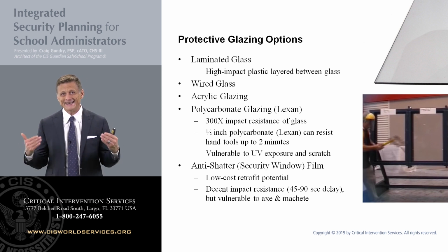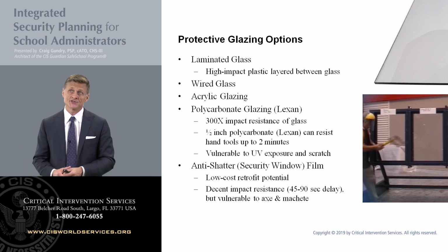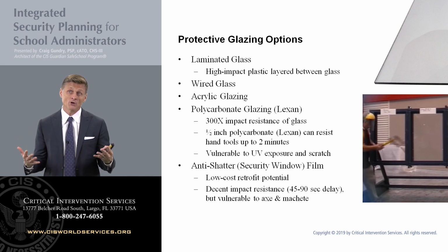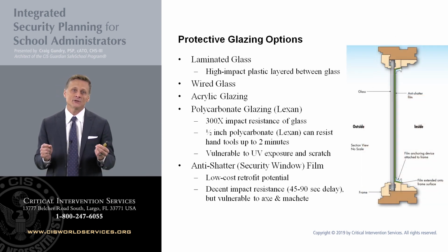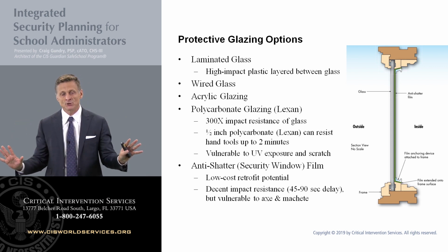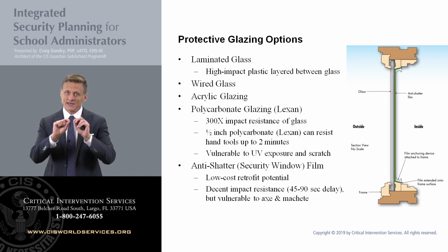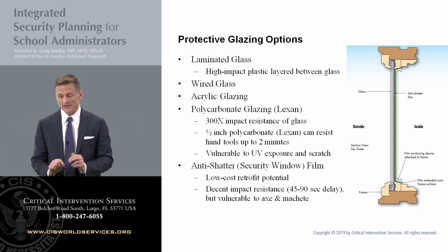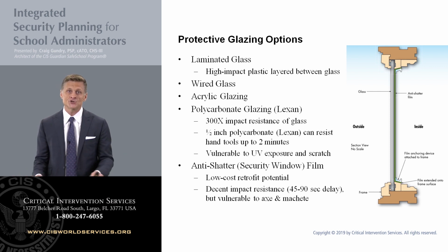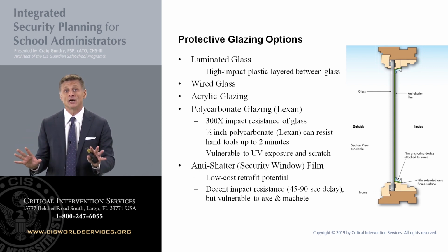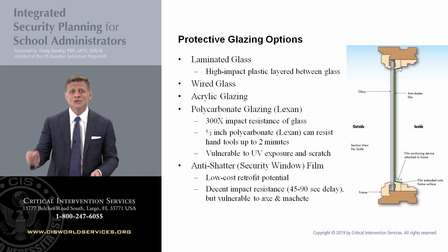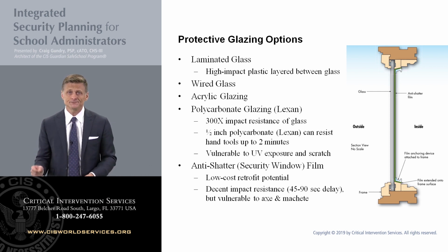Another option for upgrading existing tempered glass windows, and in some cases, especially if we have a lot of windows that need to be addressed, one of the most cost-effective approaches to this, is installing anti-shatter film. Anti-shatter film is a film membrane that is adhered directly to the tempered glass window and then attached to either a separate framing system or the existing window frame through the use of a special cement in order to retain that unit at the window when it breaks upon impact force.